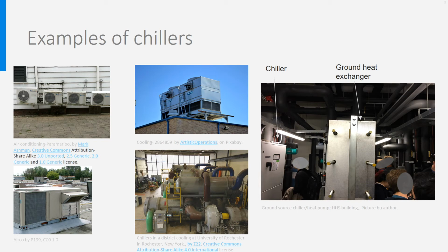In the middle of the picture, you see a big ground heat exchanger. In this heat exchanger, groundwater from an aquifer at 70 meters depth is pumped and takes over the heat rejected by the condenser of the chiller. The evaporator side of the chiller produces cold water for the air handling unit and for the floor cooling.